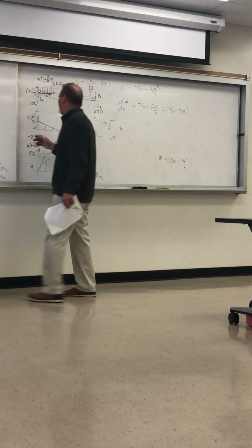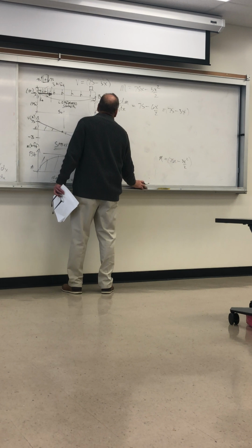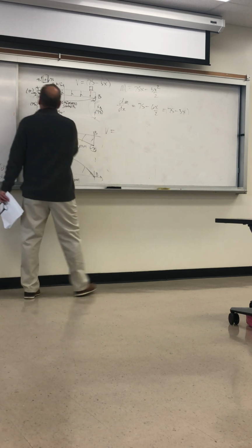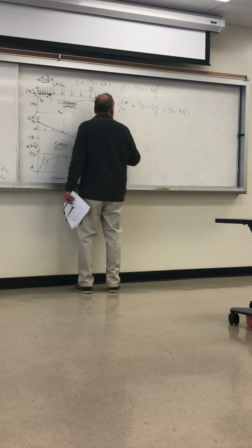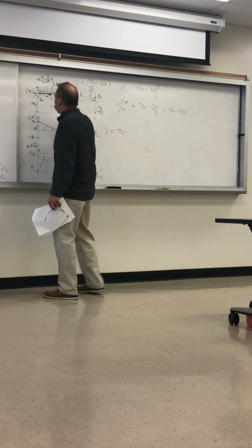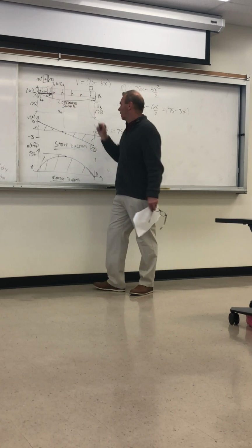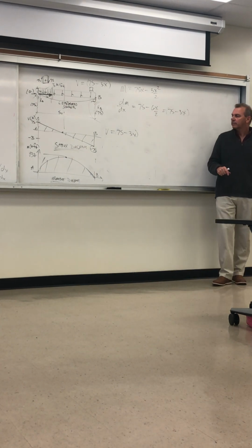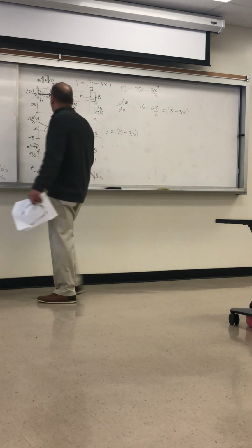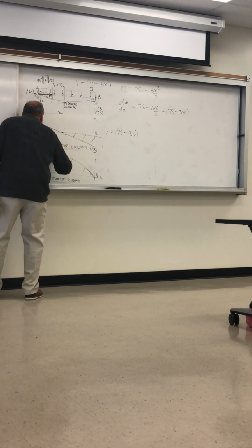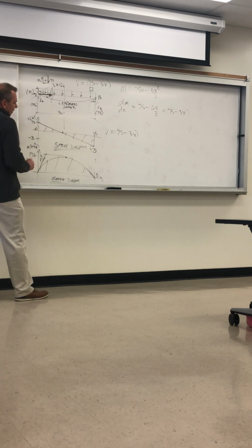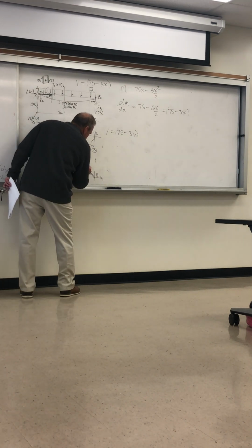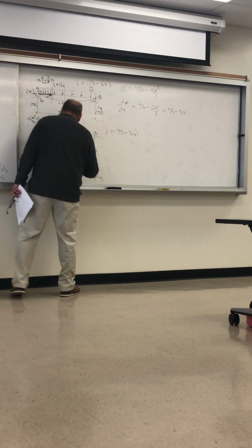And when we look at the shear expression, we see V at the beginning is 75, minus, as we go out to this location, intensity 3 times any distance x. So they're one and the same. So this is 75 here. That's the slope, this slope is 75. Notice that that's minus 75, and sure enough, the slope is negative at the right end of the moment diagram. See the slope right at the end? This is minus 75. It's consistent.